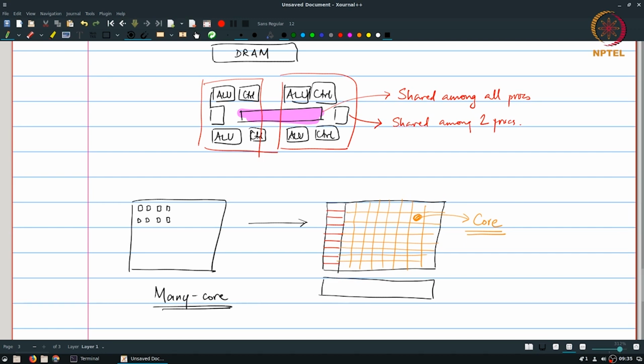The primary difference over here is how are we able to get such a large number of small cores? By stripping away a lot of the control, simplifying the logic, eliminating a lot of the out of order and speculative execution, and saying that each individual core over here is a relatively simple piece of hardware, of course still capable of computing and in fact performing floating point computations, but it just does one job, which is the floating point computation, and does it well. In that way, what we can do is create a large number of cores of relatively small size and fit them onto a single silicon die, have large amounts of distributed cache, so to say, which is split up in such a way that either single cores or blocks of a few of these cores together share a certain amount of cache memory and are able to make use of that and share information among themselves.